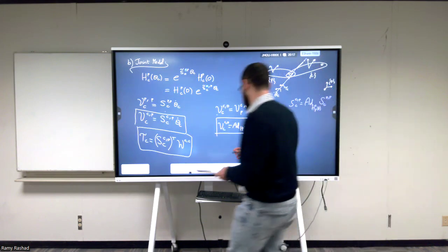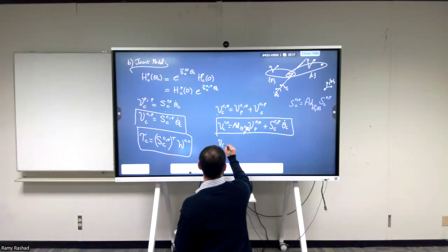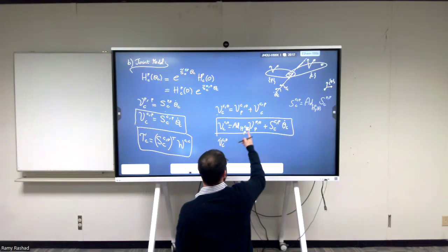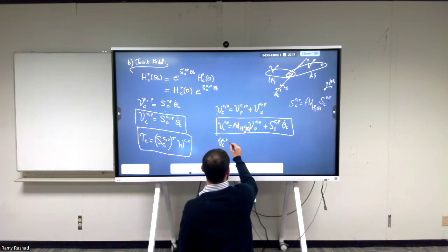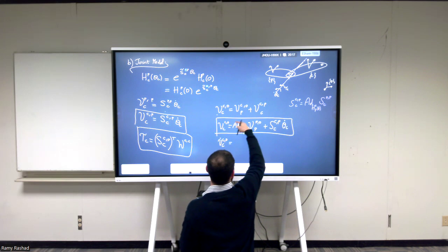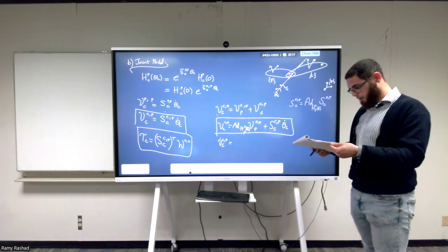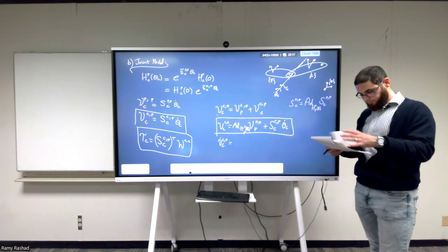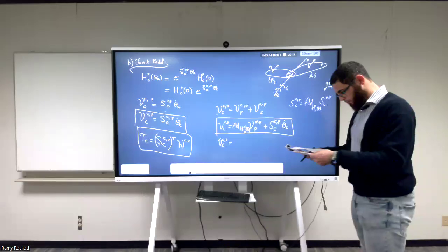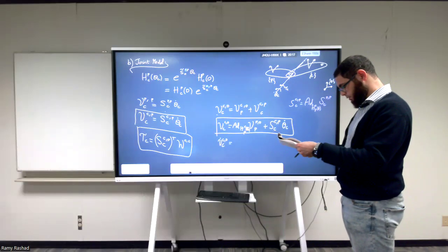So the V dot here, the VC dot, is equal to the time differentiation of the adjoint multiplied by the twist. So I have a differentiation of this part multiplied by that, plus the differentiation of that part multiplied by that. You all agree? So I'm going to have something like the time derivative of this. The time derivative of that, you should be familiar with what it looks like. Where is it? Yep, you're right. Let's see.